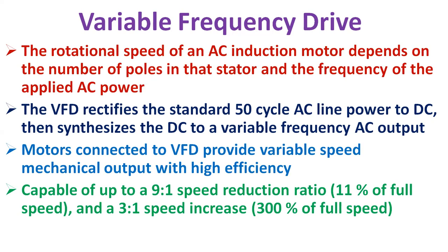Motors connected to VFD provide variable speed mechanical output with high efficiency. These devices are capable of up to 9:1 speed reduction ratio, 11% of full speed, and 3:1 speed increase with 300% of full speed. In recent years, the technology of AC variable speed drives, variable frequency drives, have evolved into